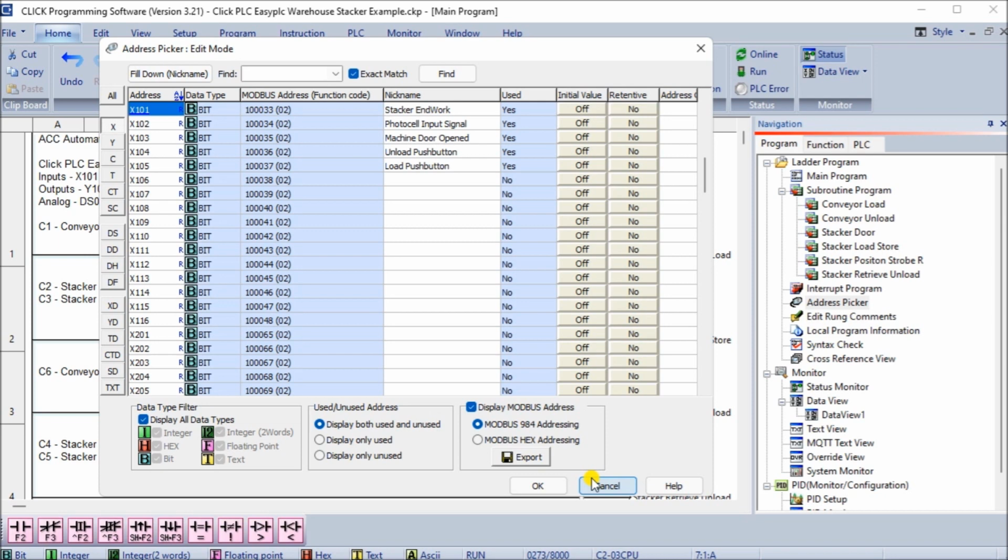Typical questions like this. Now this step is where you actually spend a majority of your time understanding everything about the operation, and it will save you time. It will help prevent you from continuously rewriting your PLC program logic. Knowing all of these answers up front is vital to the development of the PLC program.